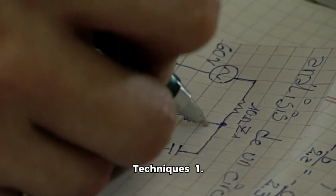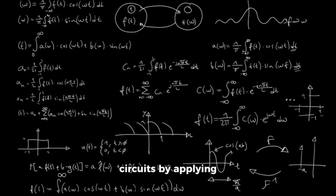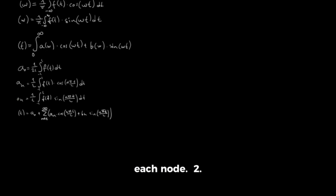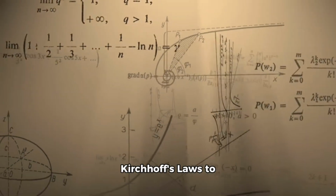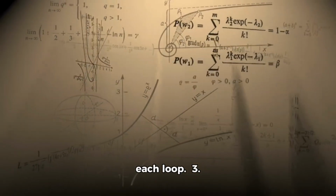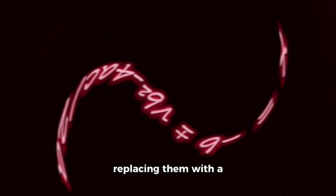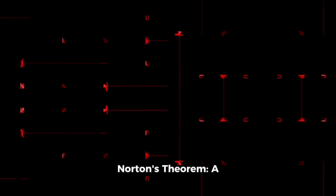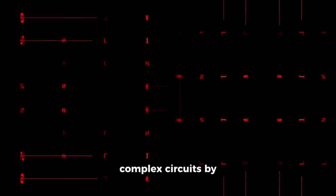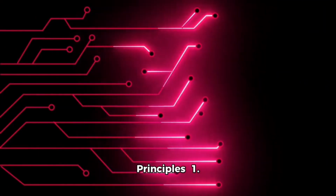Circuit analysis techniques. 1. Nodal analysis, a method for analyzing circuits by applying Kirchhoff's laws to each node. 2. Mesh analysis, a method for analyzing circuits by applying Kirchhoff's laws to each loop. 3. Thevenin's theorem, a technique for simplifying complex circuits by replacing them with a single voltage source and series resistance. 4. Norton's theorem, a technique for simplifying complex circuits by replacing them with a single current source and parallel resistance.